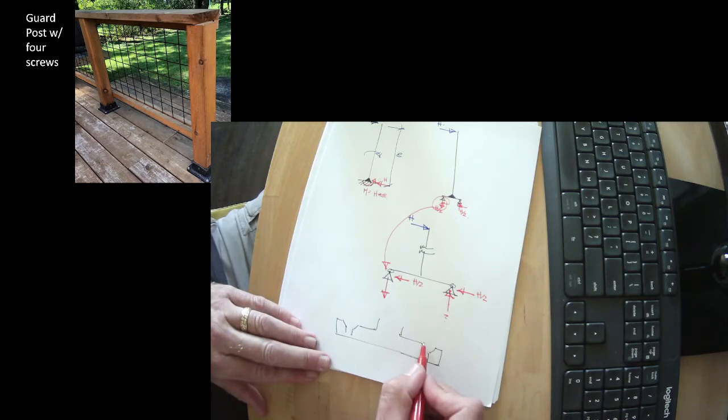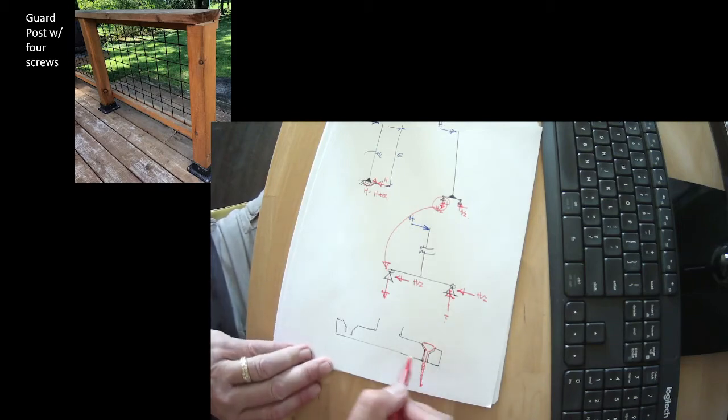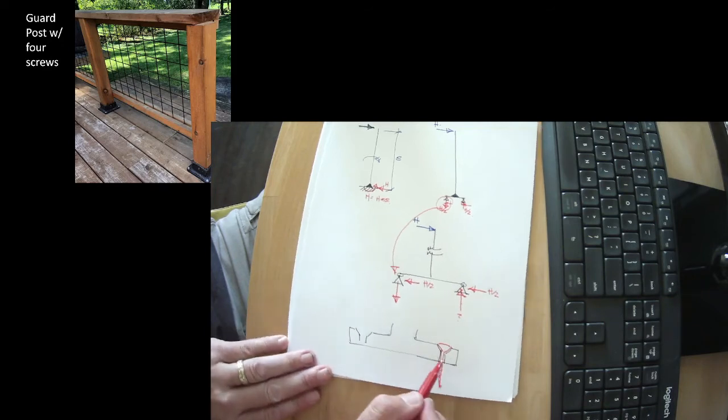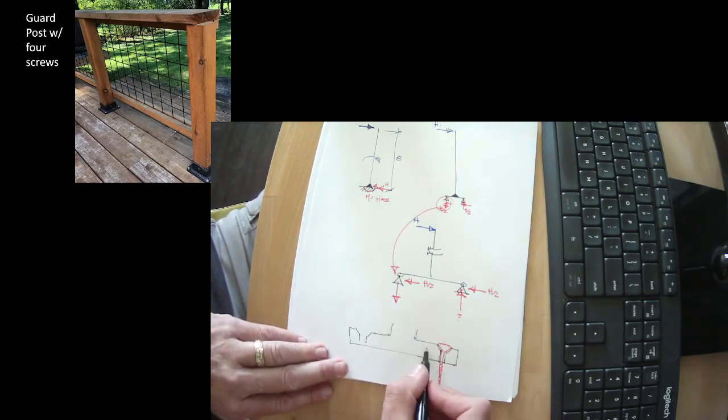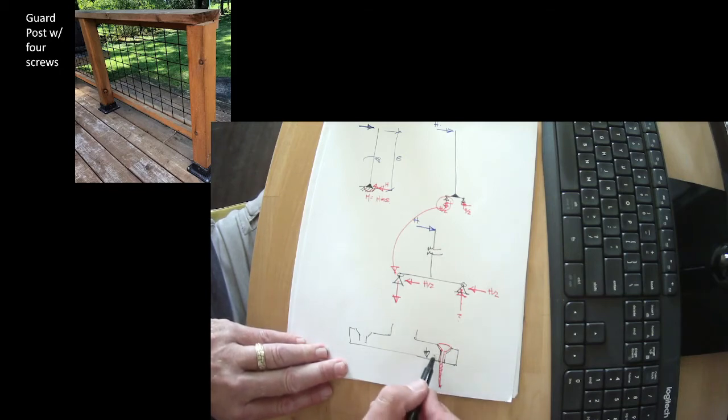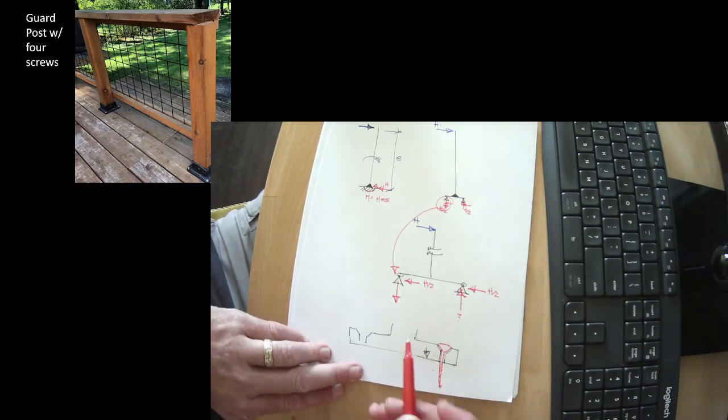And we have a countersunk screw in this hole. This screw can work in pull-out, but it can't work in compression. There's no way for this to work in compression. If this piece of molded plastic is moving down, or tries to push down, it's just going to slide in that hole. There's nothing to stop this plastic from moving down relative to that screw. So what is going on?